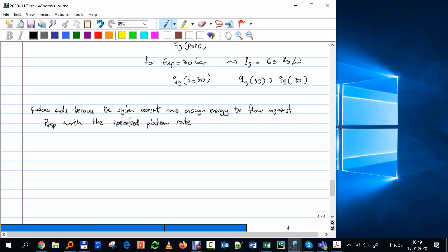So the fluid goes from the reservoir to the bottom hole, and then from the bottom hole it goes to the wellhead, and then from the wellhead usually goes to the separator. In all of these we have losses. The first is the formation, flow in porous media. How do we call that part of the system? That pressure drop, how do we call it? Drawdown, right?